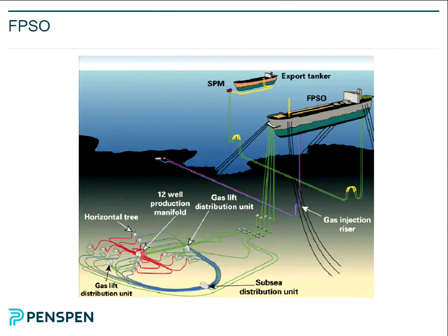So you may have about 10 different swivel connections, basically. So the FPSO can rotate indefinitely around the turret, which is fixed in space with its anchors and its risers. So you can see here the anchor chains. This is the turret configuration, bearings, and then this is the production swivel, basically. But you may have multiple.